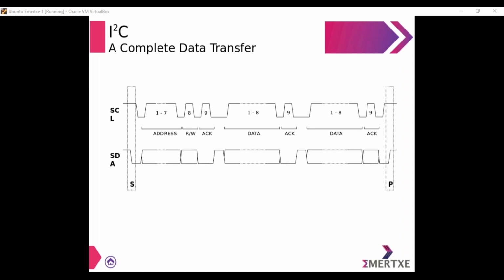the clock pulse itself. So at the high level of the clock pulse, when a device has to give an acknowledgement, the transmitter transmits a 1 and the receiver transmits a 0. That is what pulling the line up or pulling the line low represents. The transmitter transmits a 1 and the receiver transmits a 0 at the high level of the clock pulse. So that is acknowledgement.